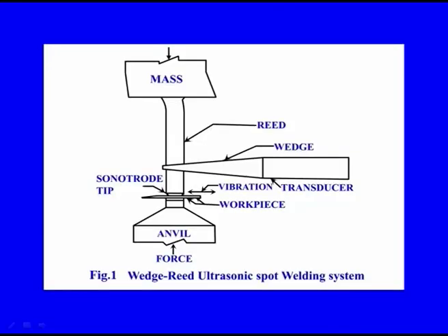So, this is the configuration used in the ultrasonic welding process, which is a solid state process, in which this is the transducer which is responsible for producing the ultrasonics. These frequencies or vibrations will be transmitted to the zone of interest through this sonotrode.